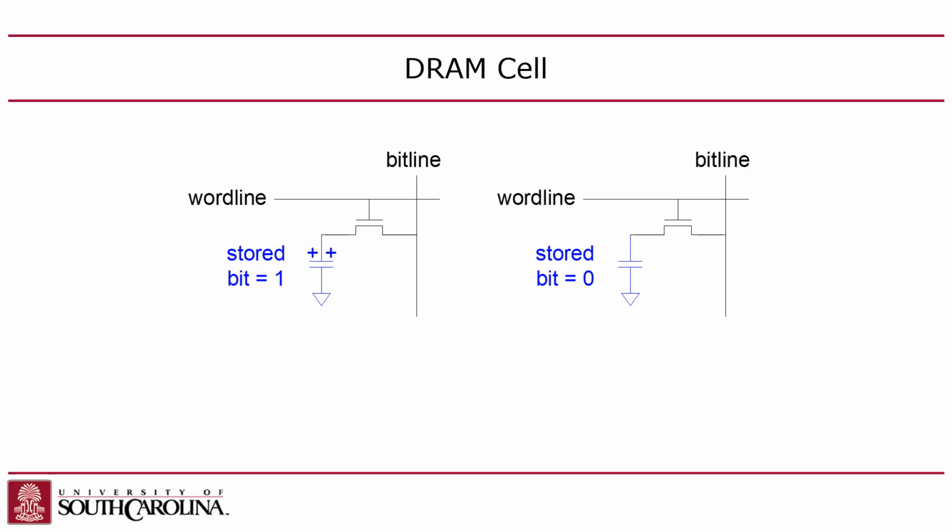So DRAM is much denser because it costs less resources, which is why we still to this day use DRAM for the main system memory. DRAMs can be bigger, and they're fast. They're still fast. They're bigger. The only problem with DRAM is they have to be on a different chip than your CPU, because they're designed in a process that supports high capacitance, right? Whereas a logic chip like your CPU is specifically designed to have minimal capacitance, because that's what makes the logic slow, right?